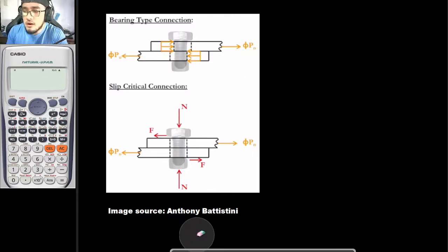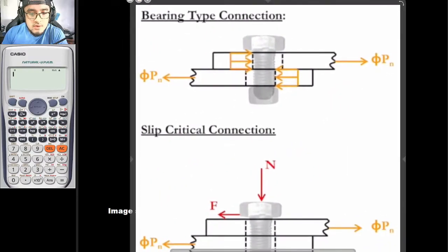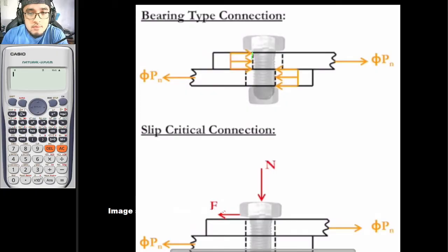Moreover, ulitin ko lang, it is assumed that the loads here are to be resisted by the contact area between the steel bolts and the surface of the member itself. So zoom in ko lang sandali para, of course, lumaki. As you can see here, there is a contact point or contact area. So ito yung sa member, then this is for the bolt. And contact pressure is basically your bearing. So, bearing.